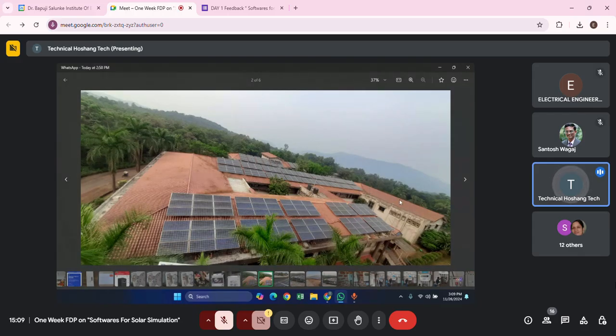When I get the new photograph, there will be some panels installed on this side, and you will see all these gaps covered. This gap we have kept for maintenance purposes. We have a small ladder over here so that we can go upstairs and do all the maintenance of both the panels. If you see this design properly, there are 9 panels on the top and 9 panels on the bottom. We have designed it specifically so that a single person with a 3-meter rope and 3-meter wiping rod can easily wipe the panels from the upper side and also from the lower side.